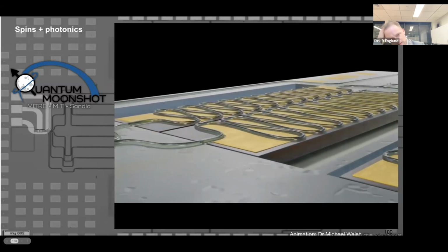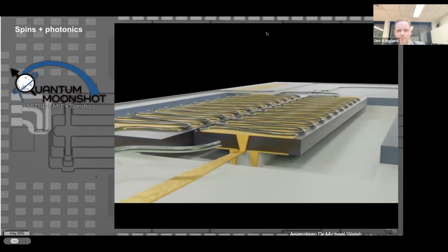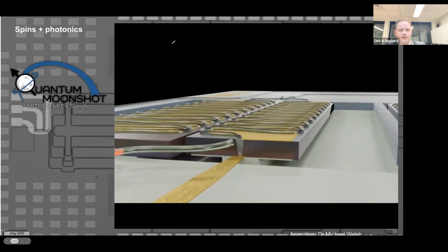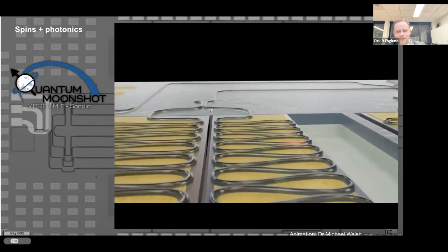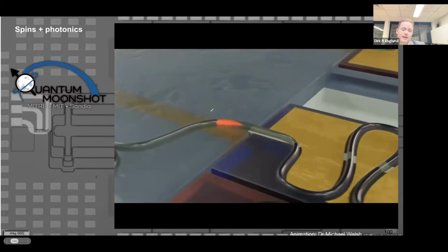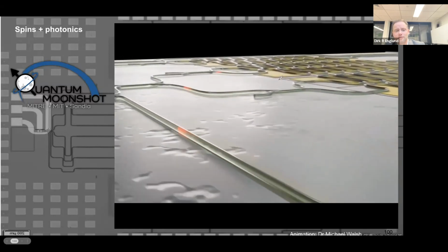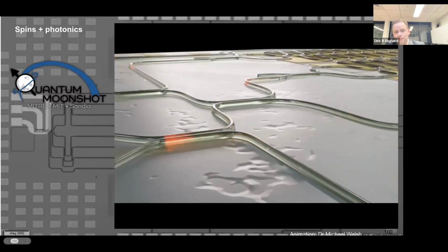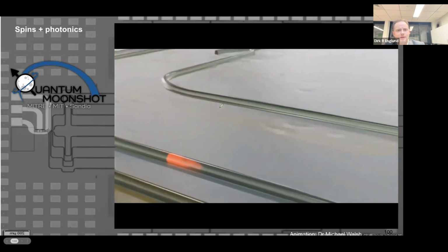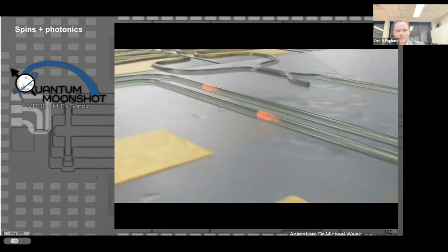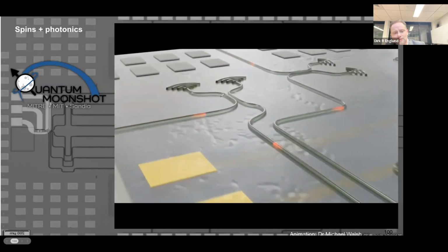Okay, next up is our Mach-Zehnder interferometer. Now, this one is a bit unusual. This is based on a strain-actuated silicon nitride Mach-Zehnder interferometer. That's because in this scheme we need things to work in the visible and with virtually no power consumption, because this has to be in a cryostat. So one of the ways to do that is using that technology. The other leading one is probably to use lithium niobate, like what CJ is developing, and some of the people in my group, and through collaboration actually with Marco's group. So that would be the photonic waveguide platform.